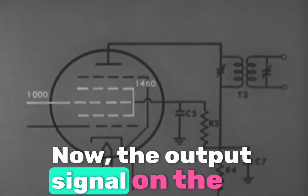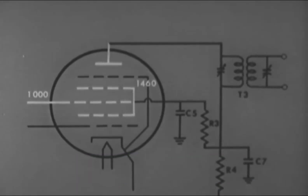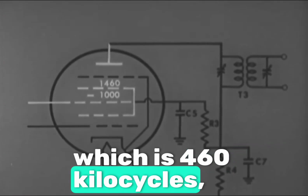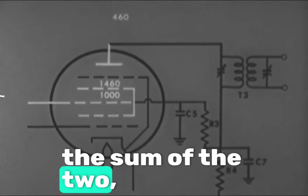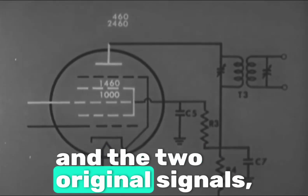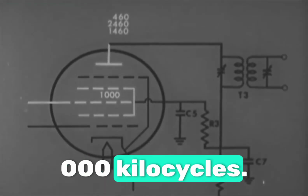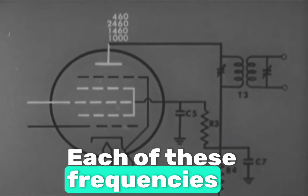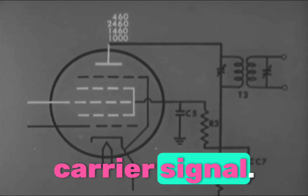Now, the output signal on the plate of the converter will consist of 4 frequencies. The difference between the two, which is 460 kilocycles, the sum of the two, which is 2460 kilocycles, and the two original signals, 1460 and 1000 kilocycles. Each of these frequencies contains the message modulation, which was present on our carrier signal.